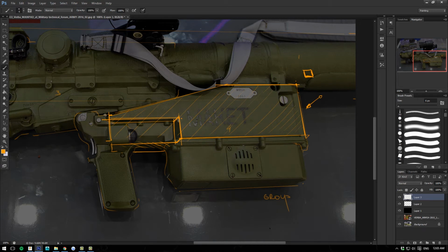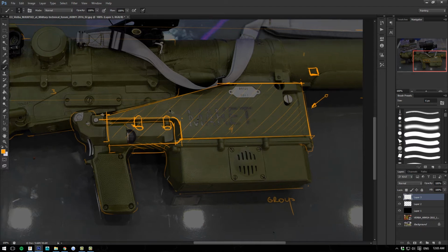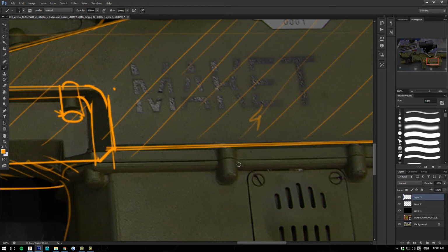So we're gonna take this edge right here and we're gonna add a fillet to the edge, which will make it rounded like that. And then we see that there's two features right here that remotely resemble cylinders, which means we're gonna create a cylinder on any of the planes. Gonna insert them right there, make them rounded by using a fillet right here, and then we're gonna merge them together, as you can see on the close-up, which these cylinders are similar to those.